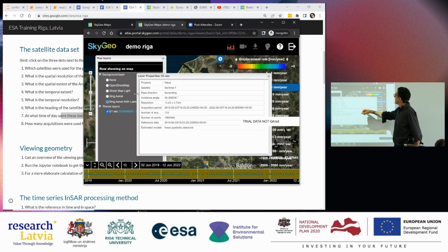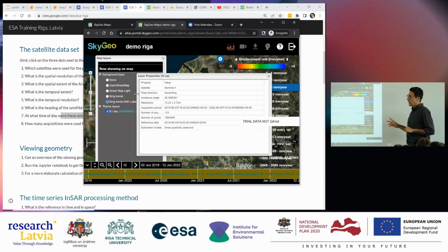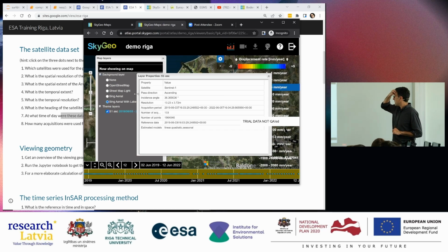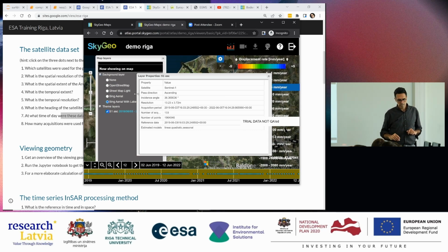And what you see here is the date of the acquisition, at the time of the acquisition, so 1604 and 29.8 seconds. And this is 1603, 29.2 seconds. So there is a little bit of difference, but basically this is sun synchronous, every time at the same time of day. And this is in UTC, right? So here I think we are 3 hours ahead with summer time, so that means that the acquisitions are at 1904, at 7 o'clock in the evening.